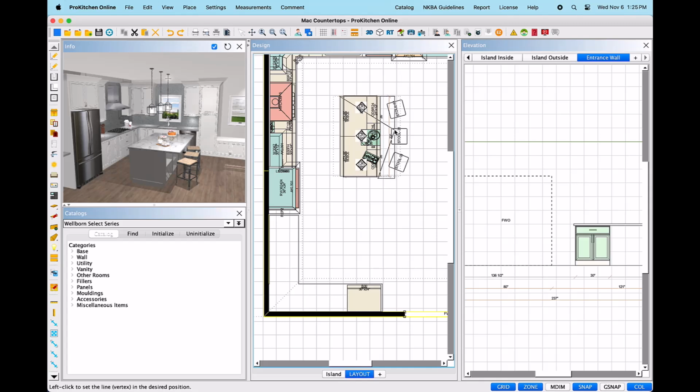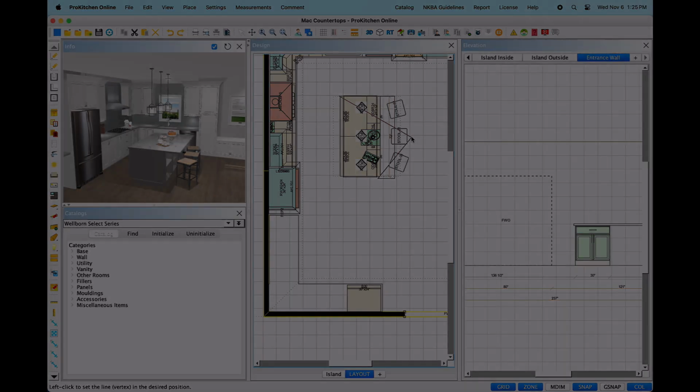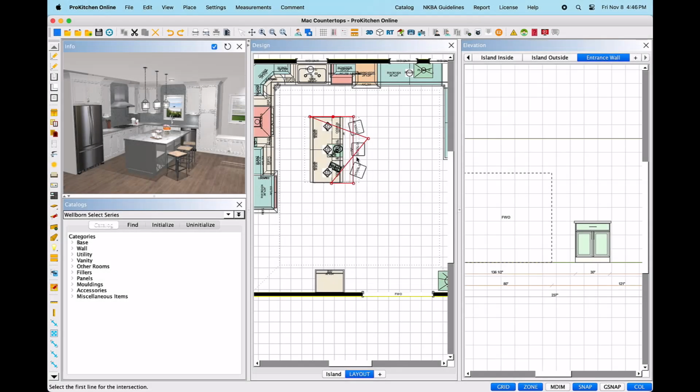If when moving a point, you end up crossing one line with another, creating an unrealistic shape to the countertop, you may hover over either of the two lines, right-click to open the subset of tools and select Intersect. Then double left-click and this will remove the intersection of the two lines at the cross point and provide you a new shape to diminish or expand.